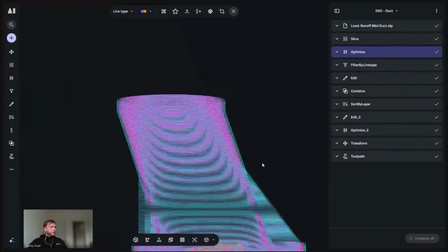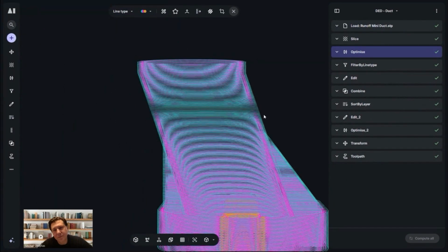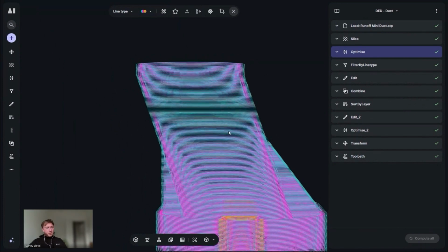We can also see that this part has an overhang. That might be an achievable overhang, in this case it's powder laser DED. But regardless, we're going to see a reduction in quality here because the laser isn't as concentrated, because you've got some step over, because the powder's going to miss a bit.